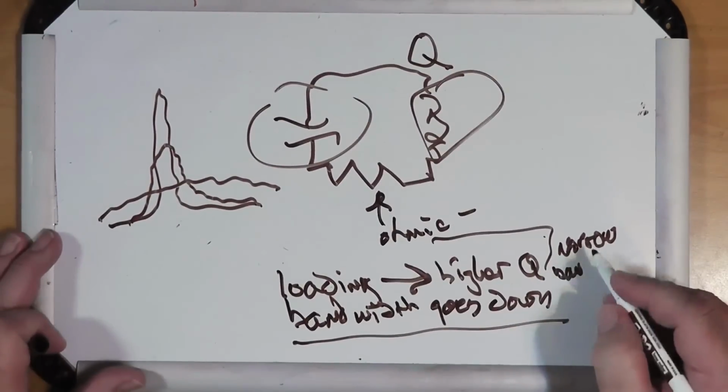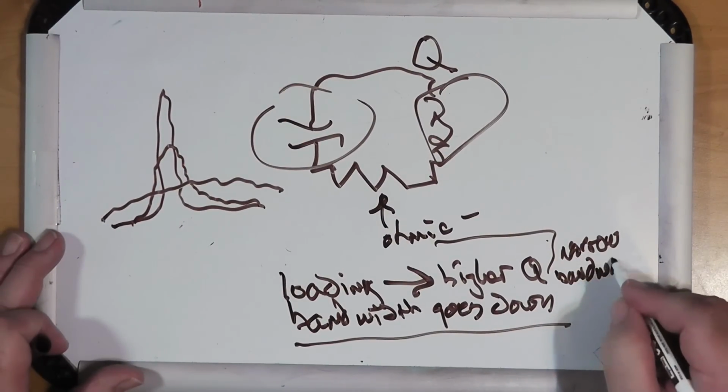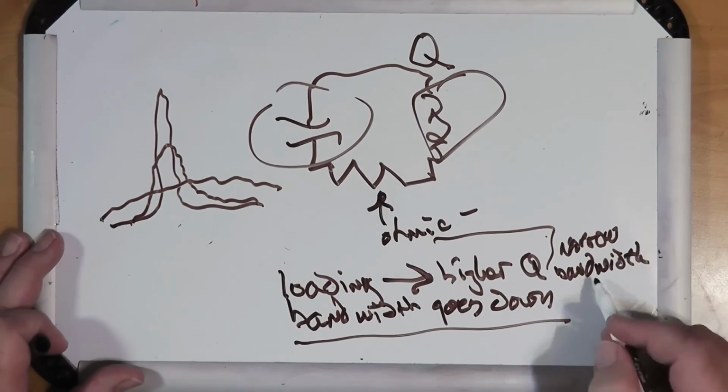So you do get a lot of current. There's a lot of current in here. Okay, and it radiates really well. This is the principle by which magnetic loop antennas can radiate really well, and so on. But you'll notice that what they trade for being able to radiate really well is bandwidth. They can only transmit really well over a small portion of the bandwidth, okay?